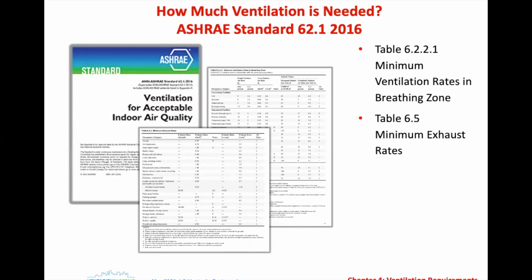So these two tables, one for supply, one for exhaust, are what is referenced and used to determine what your proper ventilation rates are in all these different spaces.